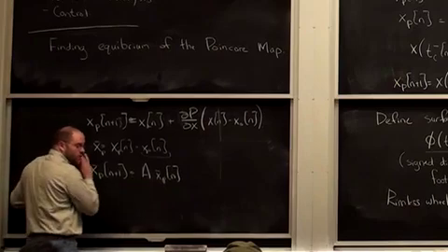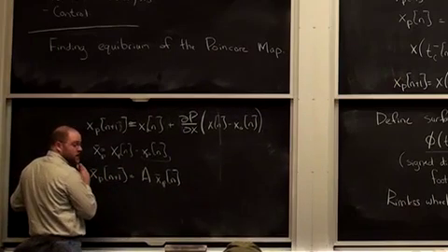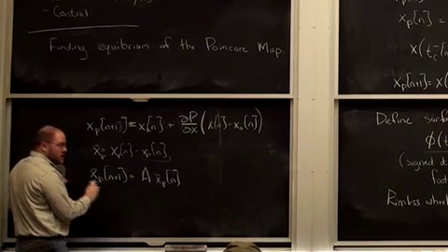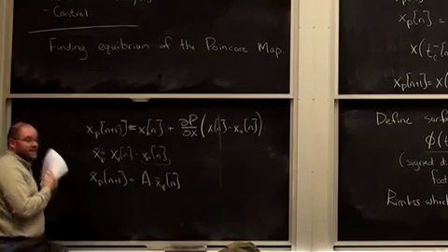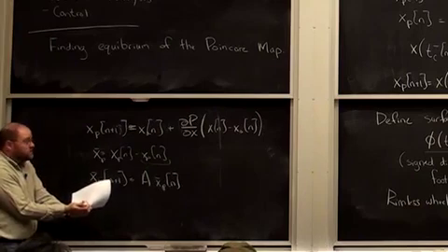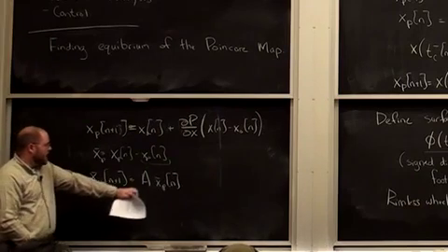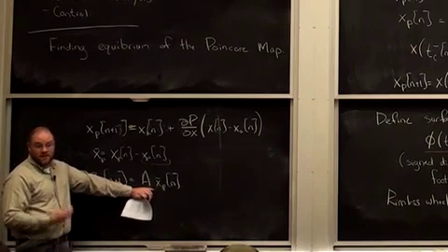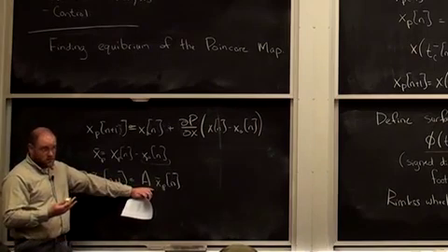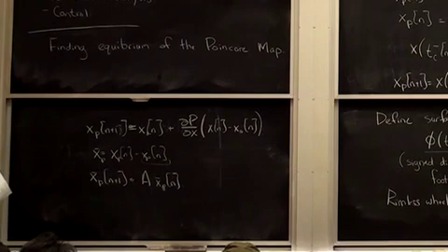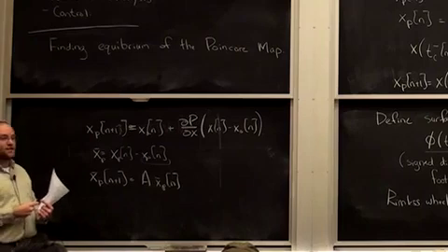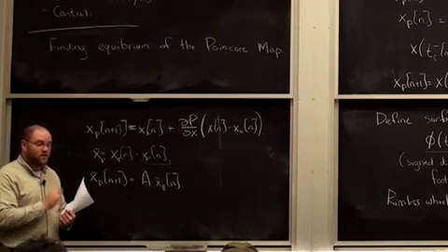So if I just cared about analyzing a passive walker, by computing partial p partial x, handing it to SNOPT or something to find the roots, I can find the fixed points, and I can also evaluate the stability of those fixed points. The rimless wheel's fixed points, if you remember, there were 2 of them. One was a rolling fixed point. One was a standing still fixed point. Both of them are locally stable.